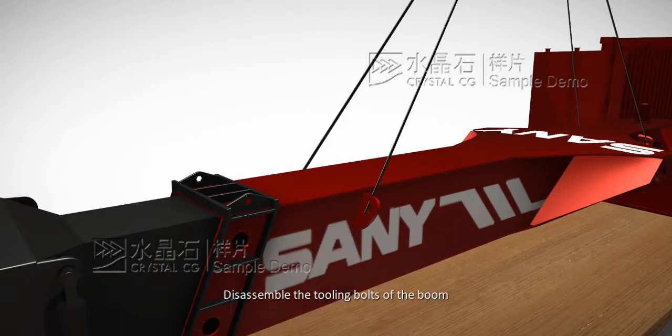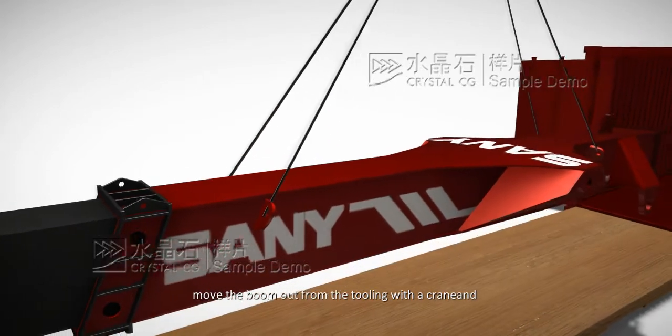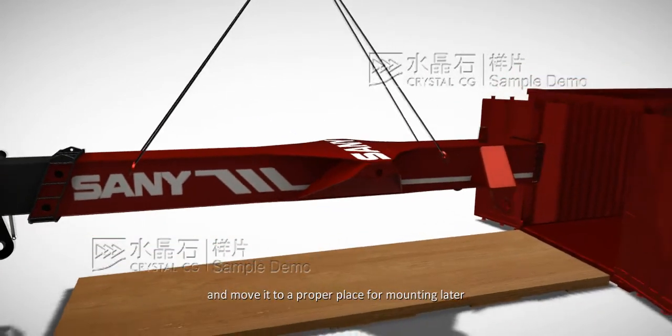Disassemble the tooling bolts of the boom. Move the boom out of the tooling with a crane, and move it to a proper place for mounting later.